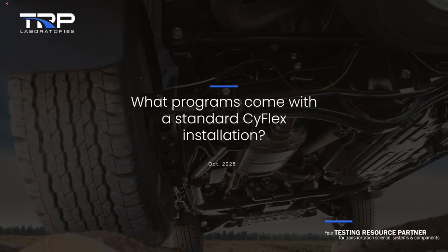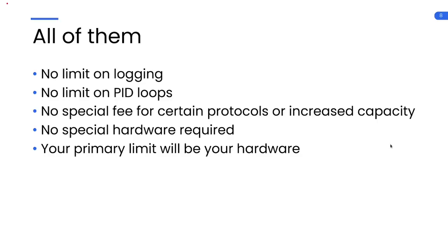What programs come with a standard CyFlex installation? Great question. All of them. So I kind of mentioned this before, but we don't have some tiered system as far as you getting our programs. We don't have a data logger that supports two variables and another one that supports 10. You just get Flogger. Flogger is our data logging program. You can put as many variables in your Flogger as your system will allow, and you can run as many Flogger instances. So you can run 10 data loggers simultaneously and output to 10 different files if your computer has enough RAM and a hard drive to support that.